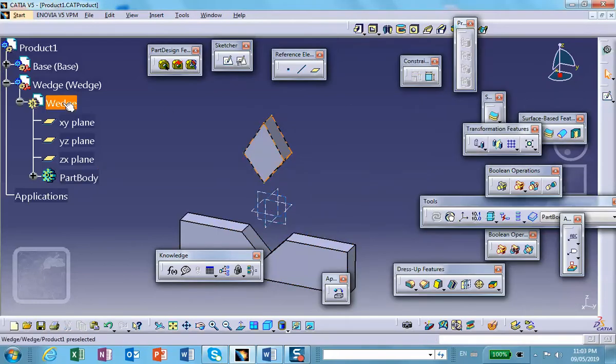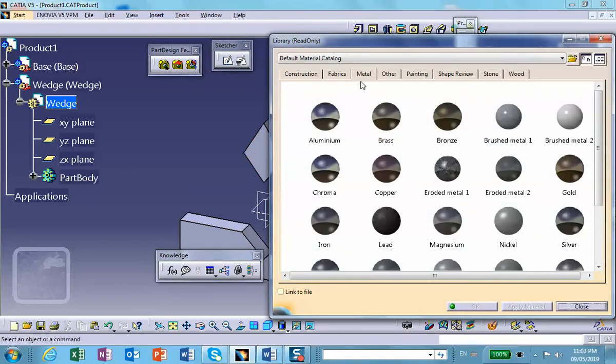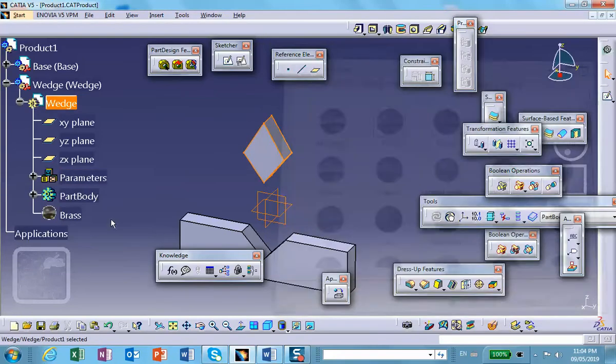So this is the same pad distance as that. Good. Now we put a dummy material on this. So apply material, metal, brass, some dummy material. Don't put it on this line, because that is going to put it on the assembly. Put it on this line. There's a single gear here. It's part design. It's going to go on the part right there. It's on the part.